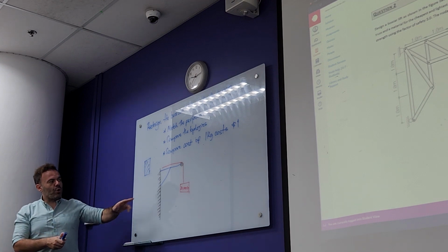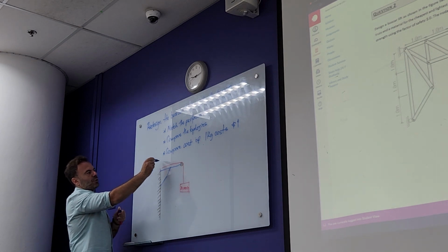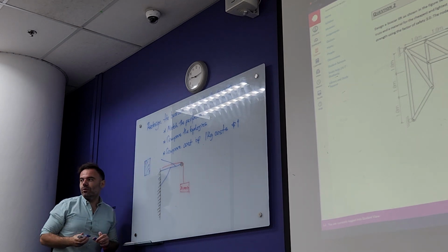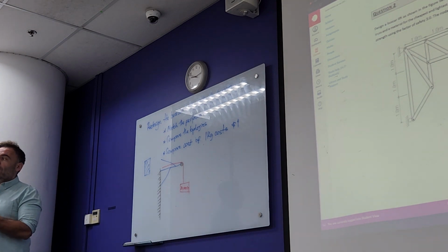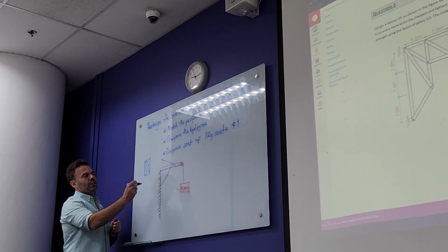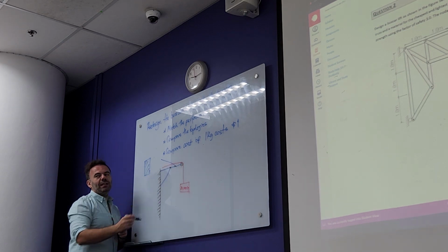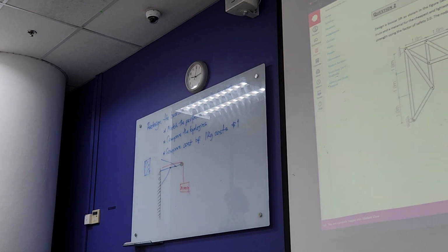We are adding components, and you may do something else. You may even have another bit that goes like that. I don't know. So the idea is to reduce the weight of it and therefore cost. But then you may argue, look, more components that are added, I have to weld here, I have to weld there, have to do those things. Well, that's something we can balance out with the costs of manufacturing. And that's basically what FEA engineers do.